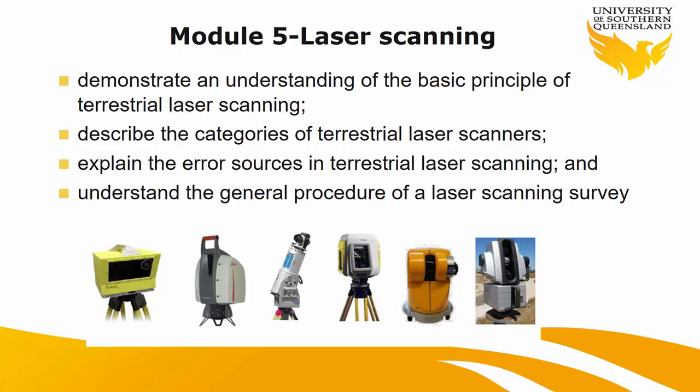criteria are. For example, if I want to go out there and set up my laser scanning, what are the things I'm looking for in terms of constraints on where I can put my station? Do you remember we had this in the lecture? You don't want to put it too close to a building, for example. You're not going to have good coverage. There is a distance constraint. There are other constraints like reflectiveness of the objects. All those things can affect it.